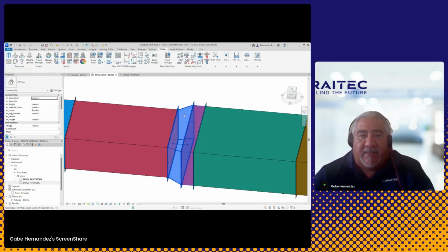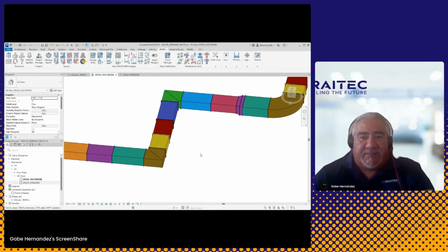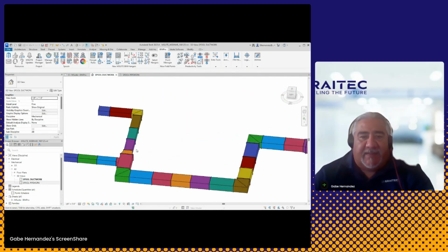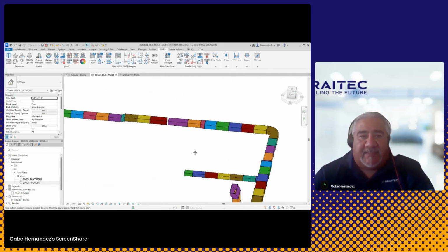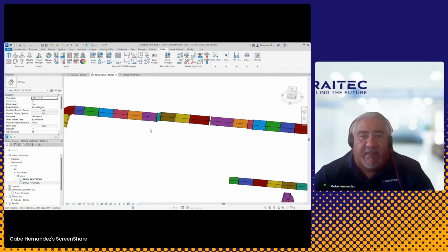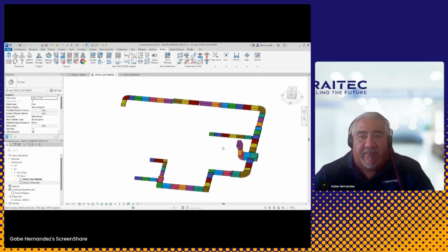There's a couple of different selection options here, but I'll just go ahead and do them both together. And then again, you get to choose which one. I'll just keep 12. And I've merged those spools. So again, you can go through this and fix things, merge spools. Maybe there's too many single pieces. That's kind of the whole point of the single duct for this command, right?